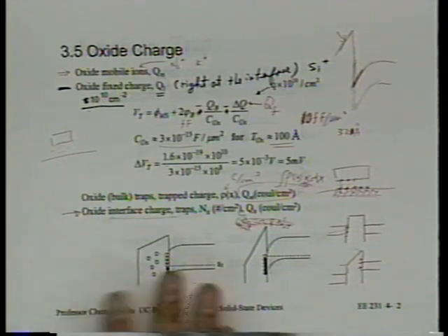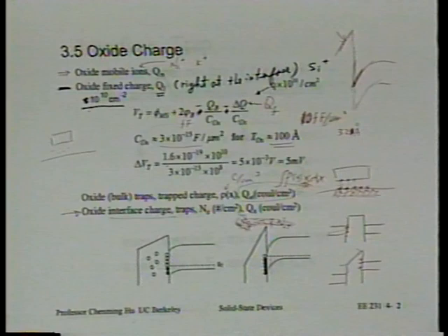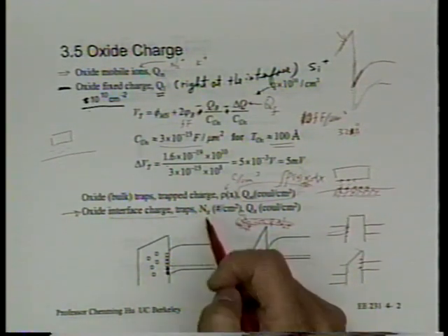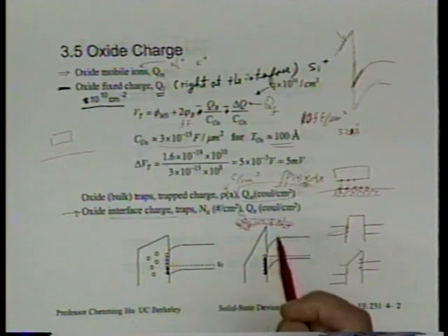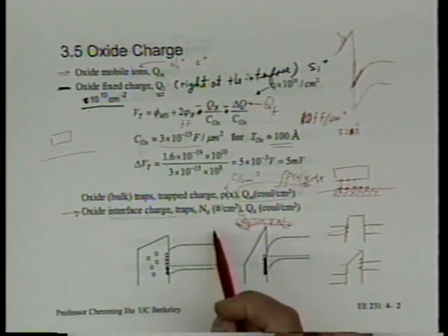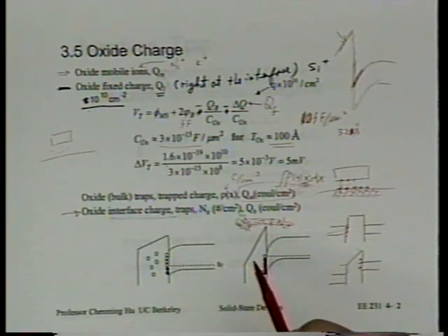If you put other dielectric next to the silicon, you actually get a large number of states in the band gap. But with good SiO2-silicon interface, the interface state trap density truly is fairly low, but often can be a problem. Now, what's the density here? Let me give you several numbers.